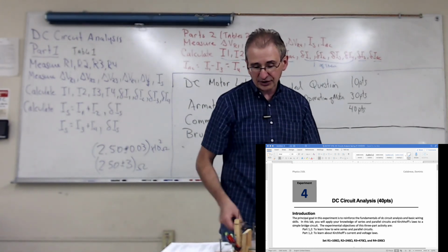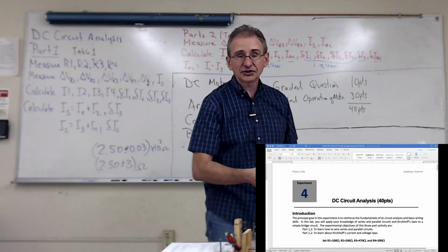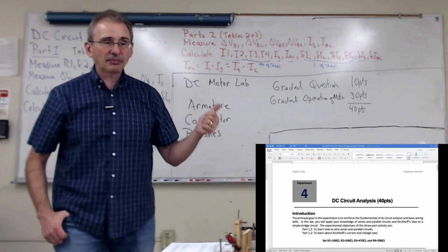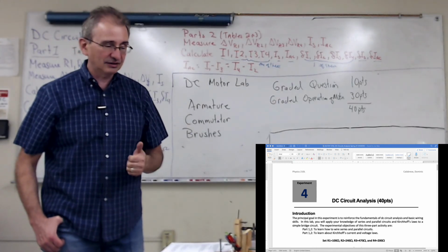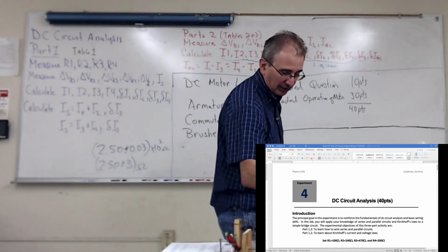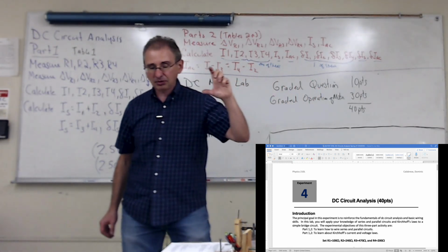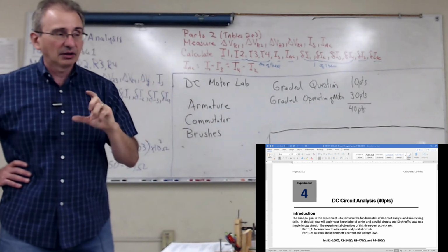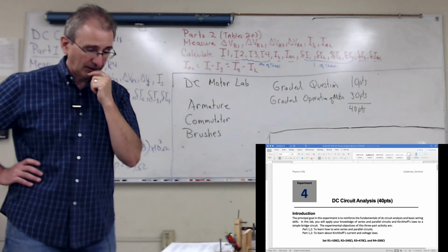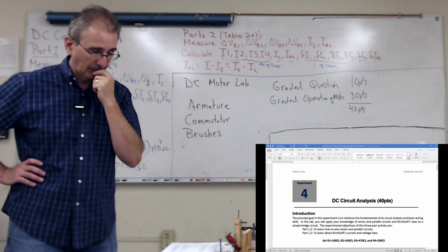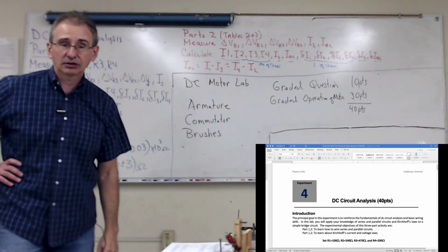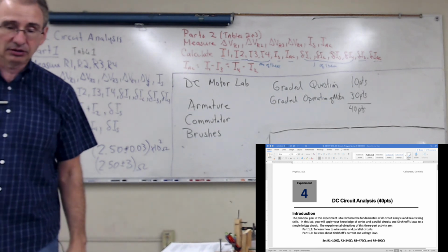If you're doing this at home and you need more than 2 D-cell batteries, you've got to go buy more batteries. Don't use the 9-volt batteries because the internal resistance is higher. And I won't guarantee that the power supply that comes with your Ohm's Law lab will work for you because it's current limited. It might or it might not work. I'm not sure. The higher the voltage, the less likely it'll work.